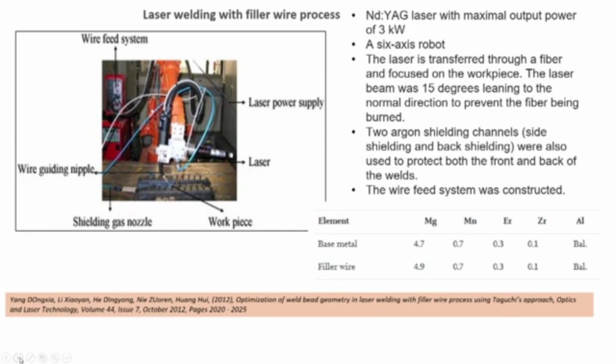So, here we are having the workpiece. This is the workpiece. There is a laser. This laser is of Nd:YAG type solid state laser, and it provides a highest power of 3 kilowatt. Here you can see the laser power supply. Now, as I mentioned, due to more vaporization there is a need to have the filler material. So, we can have a filament of the same filler material which can be used to melt and deposit at the junction of the joining.